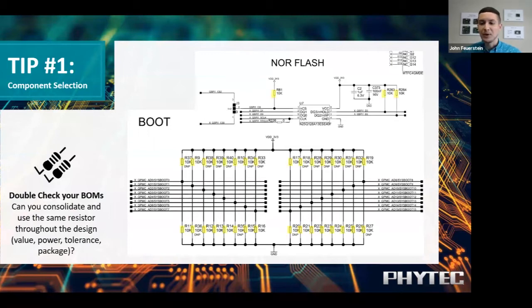During schematic capture, I'm pulling these in. Maybe I go grab some lunch, come back, and start working on the NOR flash after I'd already done the boot circuit. Then without thinking, I just pull in some random 10K resistors, not really thinking about what I used before. That seems fine, right? It's just a 10K resistor. At the schematic level, they're the same, it's fine.